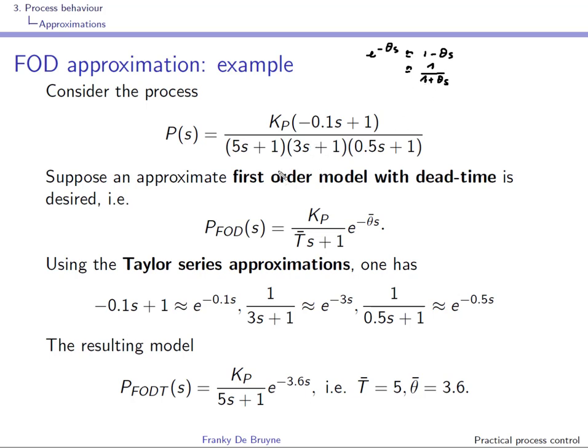So what we'll do is first tackle the lead time constant. You can use this formula over here to replace it by a delay, and we'll just keep the main time constant, right? And the other 2 time constants will be replaced by a delay using this formula over here, right?